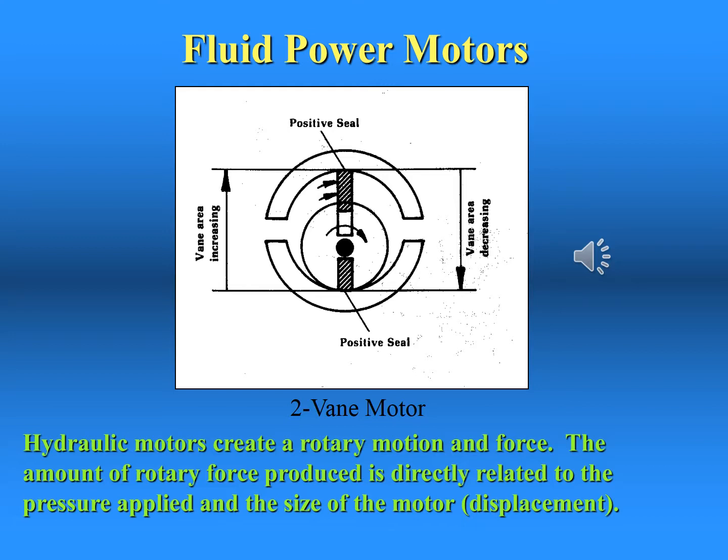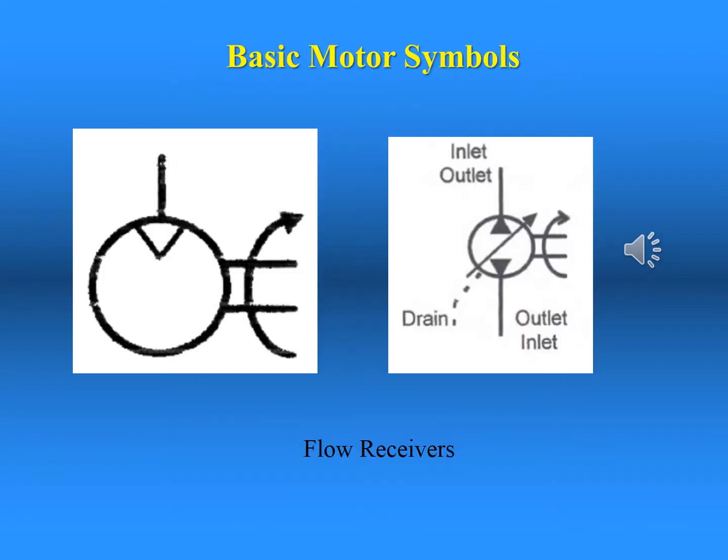Pneumatic motors often have a muffler attached to the outlet port to reduce noise. The basic symbols show the arrows pointing inward. This device receives flow and produces rotary force for mechanical energy. The amount of force is proportional to the motor's physical displacement and the applied pressure.